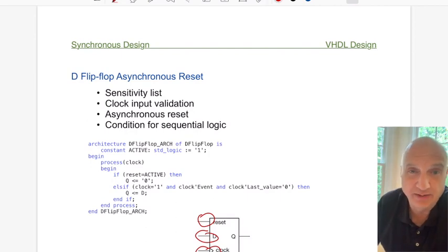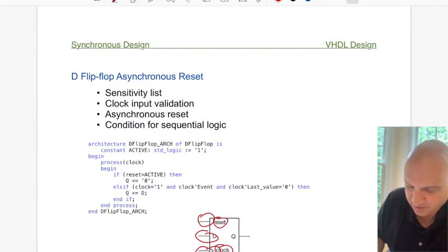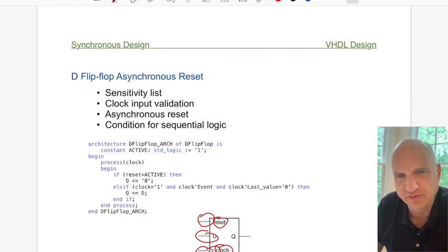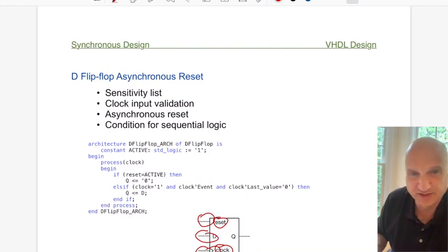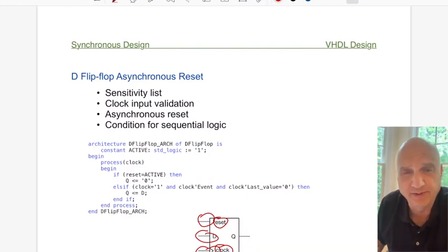Typically the naming conventions that we go by are lowercase for the signals, but since we're dealing with a fairly common element, I figured we would stick with the notation of simple D and Q for a flip-flop. The reset input and the clock input should be part of the sensitivity list, because if either one of those values changes, we want to ensure that the flip-flop process gets executed, right? Because they have an immediate impact on the output.